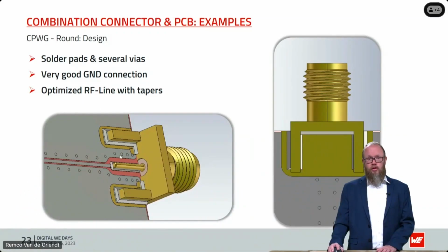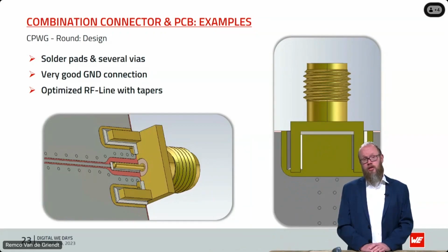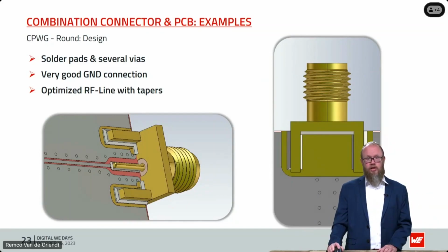Also, you have line tapering, where you change the distance between the ground plane and the transmission line and the pin itself. Because there is a big amount of brass in this connector, you get capacitive parasitic influences there. These could cause a big change of your characteristic impedance and a big problem of losses. If you want to reduce losses, you can use line tapering. You can calculate it with all the formulas I already mentioned in the earlier stage of this presentation.